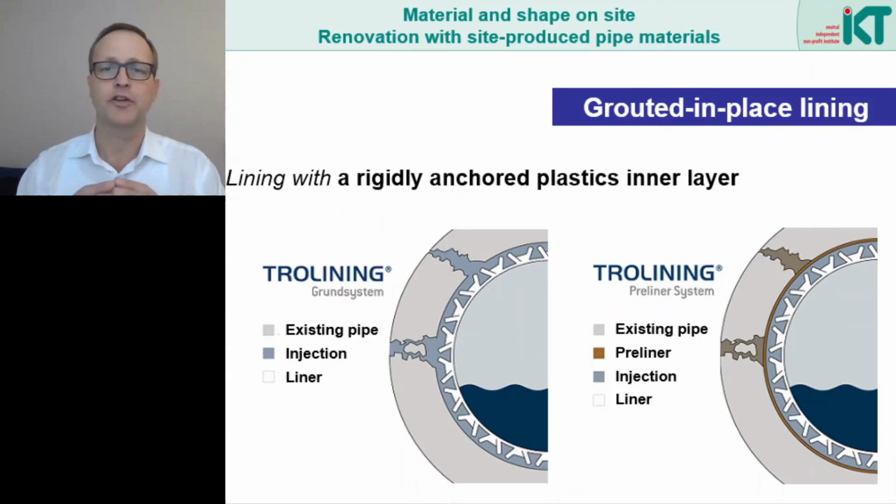With regard to the use of mortar, we distinguish between two cases. In the first case, here on the left, the mortar can also penetrate cracks in the pipe or even cavities in the bedding. Thereby, the mortar also stabilizes the old pipe and the bedding. However, there is then a danger that the mortar will run away into cavities in an uncontrolled manner and seeks its own way in the underground.